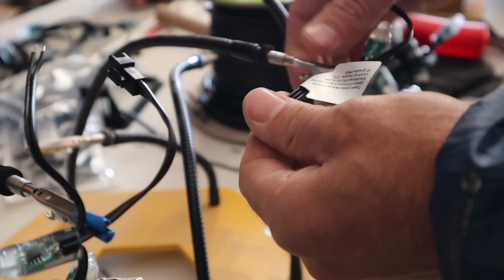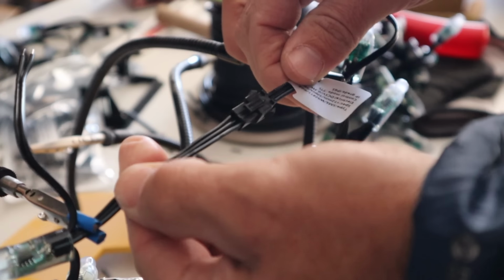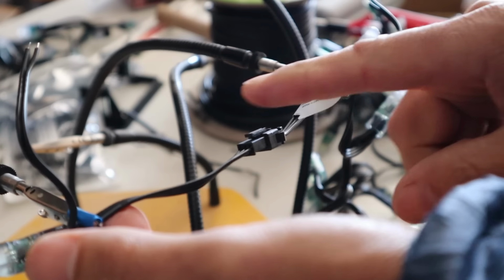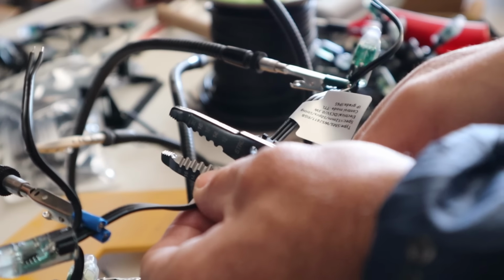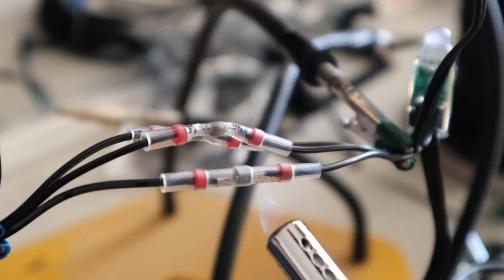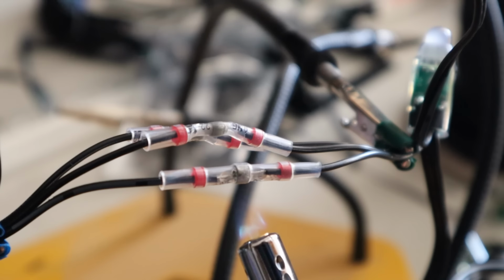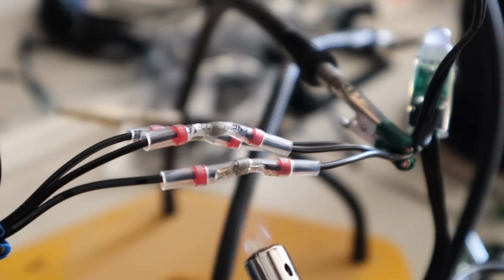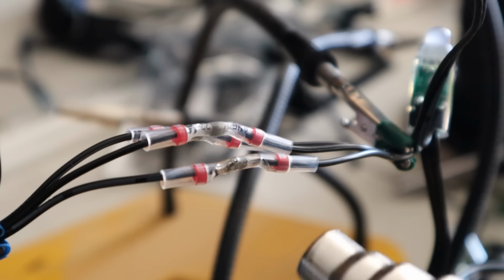When it comes to hooking the two strands together, they come with these connectors, but those aren't necessarily waterproof, so I wanted to replace them. So what I would do is plug them together first. That way I made sure I had the wires in the proper order, and then I would cut the connectors out, and then strip the wires back and use these solder butt connectors with the heat shrink built in, and I would use a combination of a lighter and a heat gun in order to do these connections. And that way I could ensure that all of these were totally waterproof when I was done.